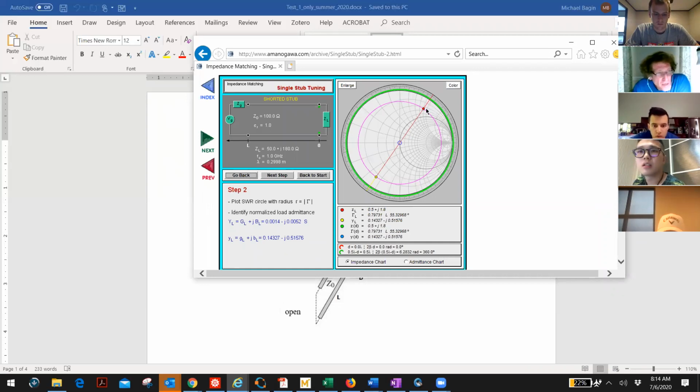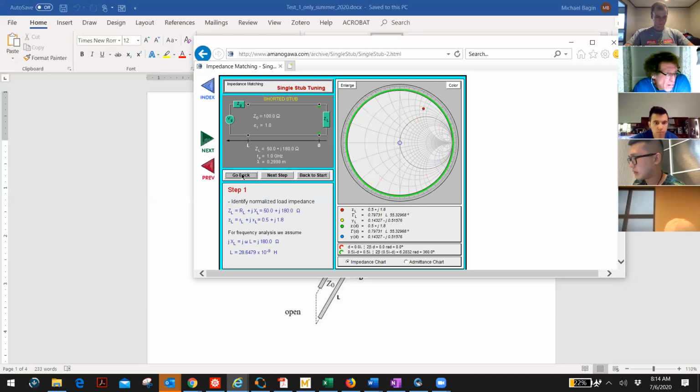when you come in, your load or your normalized impedance is here, you go to the opposite point, YL. Now, when you know you're going to have an open circuit stub, so an open circuit stub has an infinite impedance, that would be here, and the admittance would be over here, it'd be 0. And if you're moving from here to make this minimal distance, you want to have positive values that you have to add, which means you want your normalized admittance to have a value of 1 minus J something. And I hope you're getting what I'm saying.